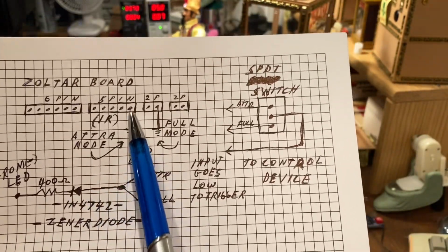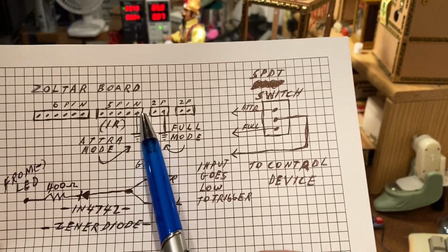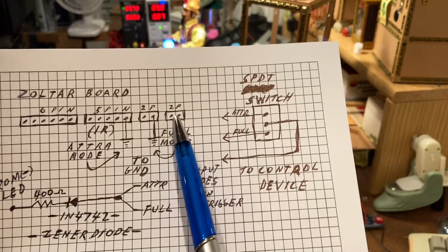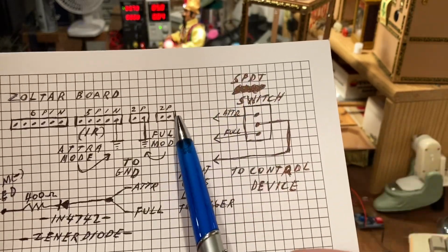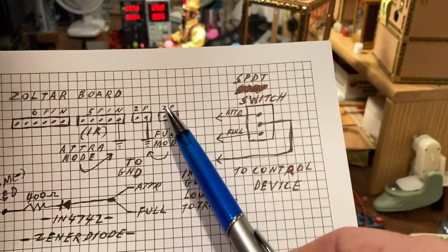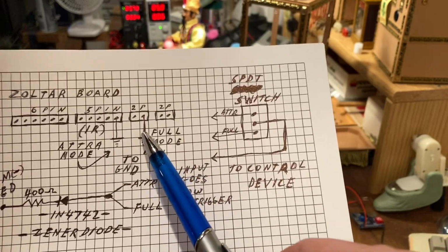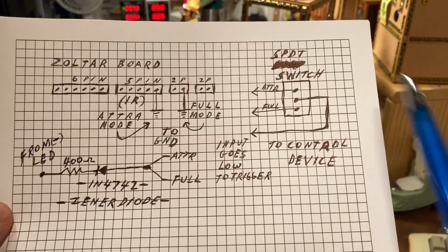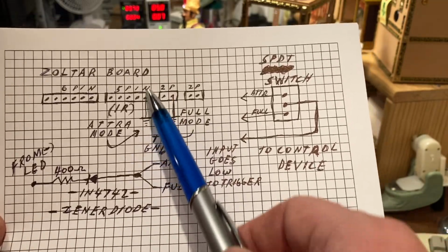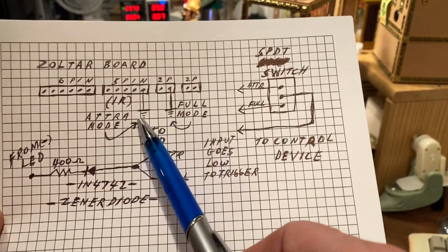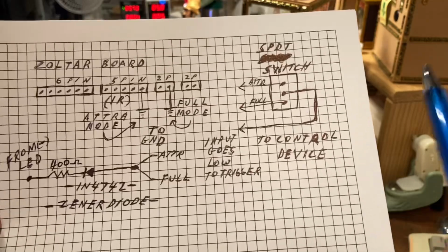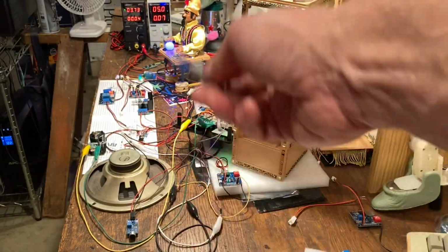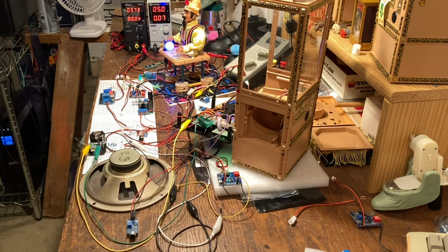And then your attract mode is on pin number 1 on that 5-pin IR header. All you gotta do is count. Go to the first 2 pins on the very bottom of the board, 1, 2, and 3. For the full mode, take this one to ground, and it'll trigger full mode on Zoltar. And if you take pin number 1 on the IR and ground it, he'll fire up in track mode. So all these little devices I have hooked up here can be